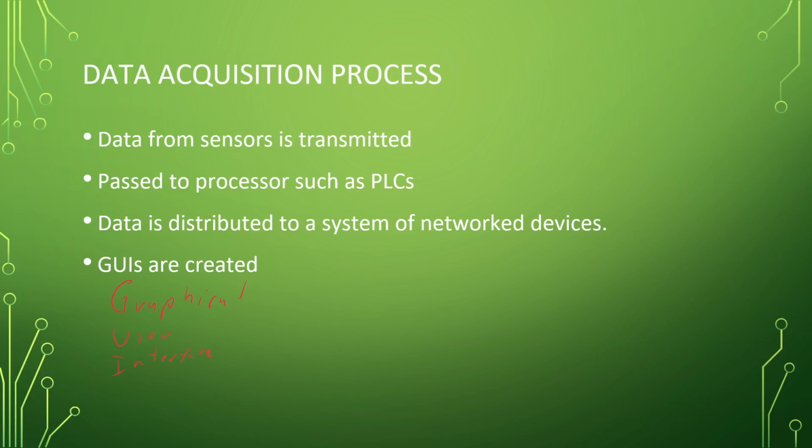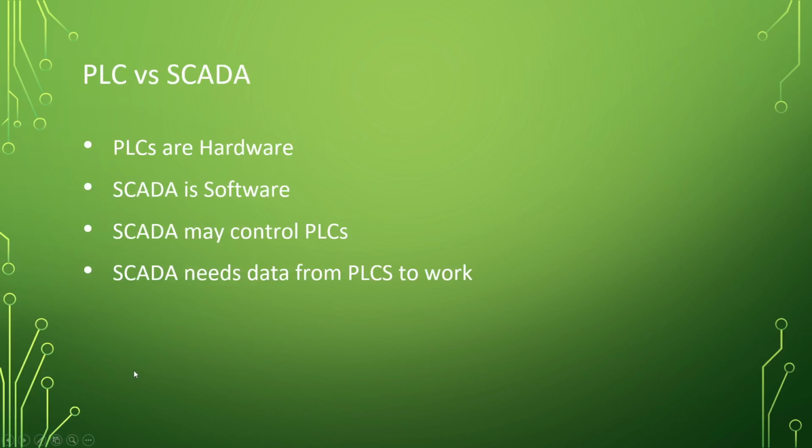And the one thing you might ask, probably not going to ask, is PLC versus HMI, or not HMI, versus SCADA. The key here is it's not one or the other. You either have a PLC and you're using SCADA with it, or you don't have a PLC with SCADA. SCADA isn't replacing the PLC. The PLC is still the important process. It's still gathering all the input, still actually controlling the outputs and all those other fun things.